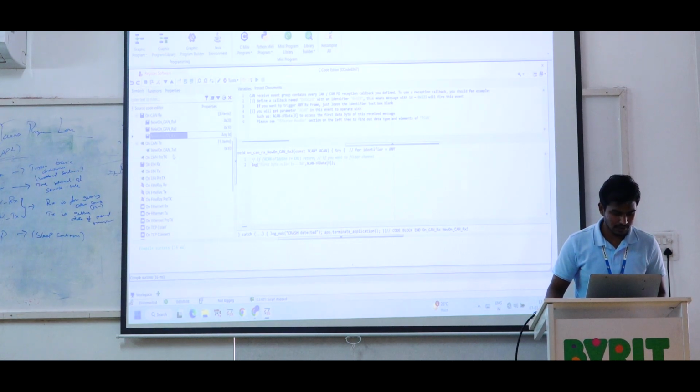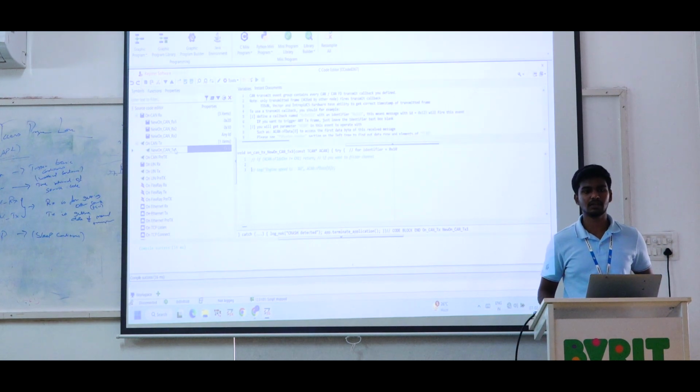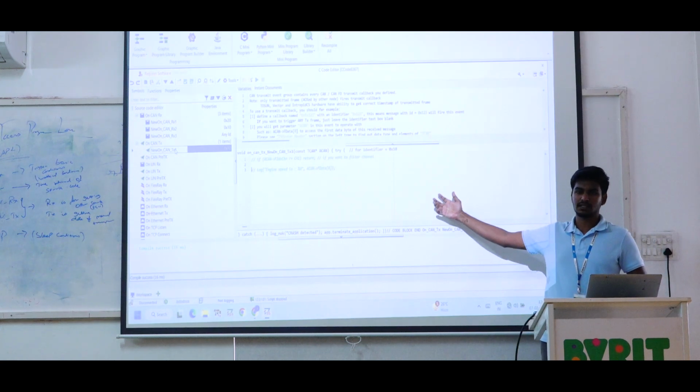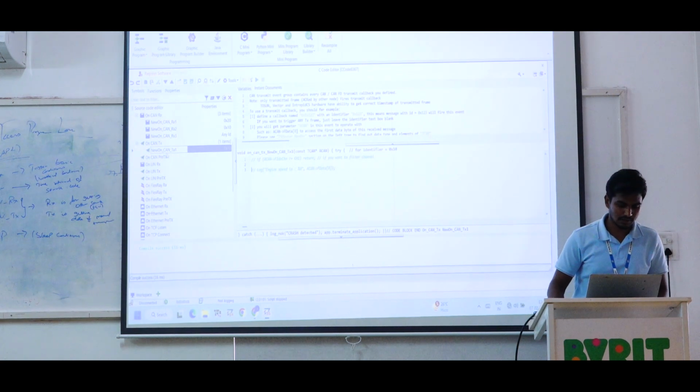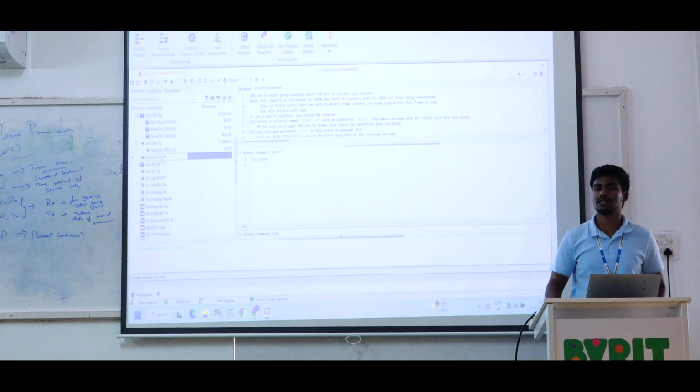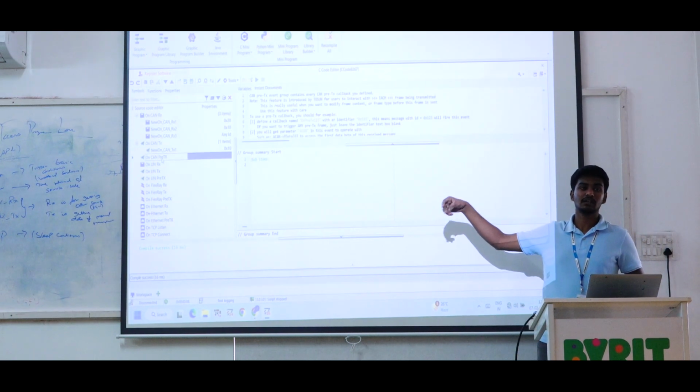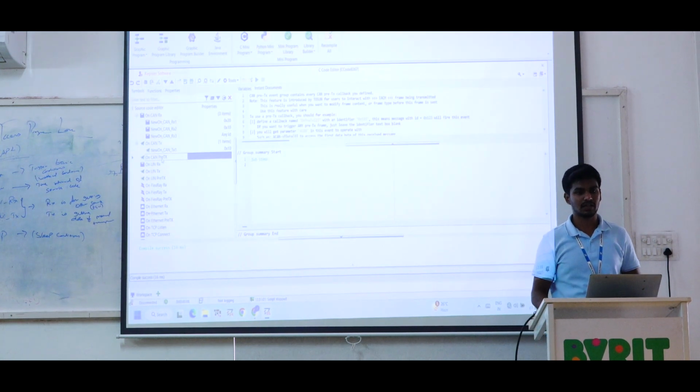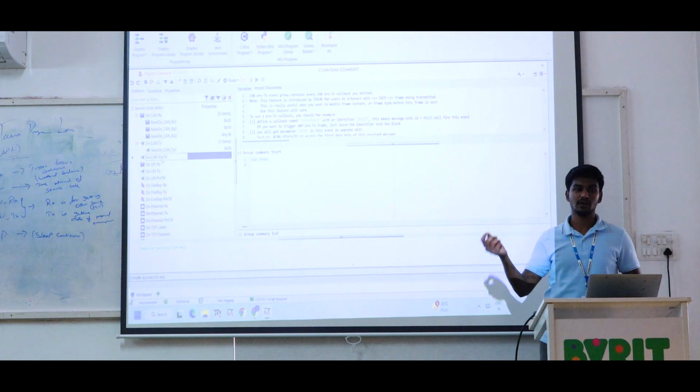Okay. So next one, TX concept. This TX is also the same thing. So whatever we transmitted, we have to check in the condition. So CAN pre-TX is there. Pre-TX means nothing but we are able to modify the byte values, whatever we are going to transmit. So for that we need the help of RBS.